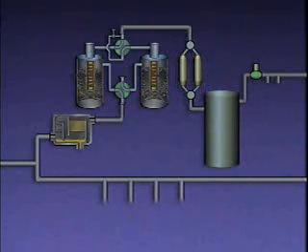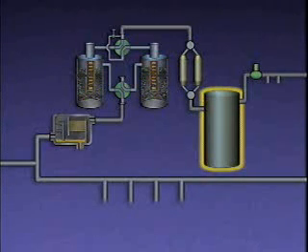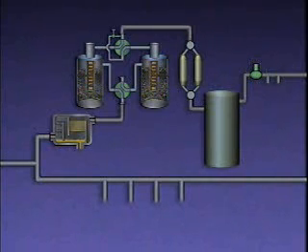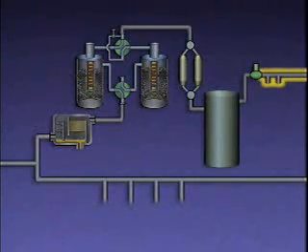Dry filtered air that is suitable for use in a control system is typically stored in a receiver until it is needed. Then it is sent to a pressure-reducing valve. The valve's function is to reduce the 120 psi air to 50 psi for use in pneumatic instruments and devices throughout the plant. The compressed air coming out of the pressure-reducing valve is distributed by an instrument air header.